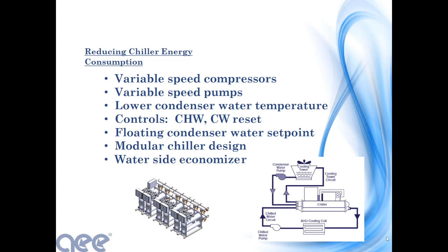Get that down where, and every chiller is going to have a minimum. It might be 65 degrees. So if it reaches that 65 degrees, then you ramp down the cooling tower fans to make sure it doesn't go below that.